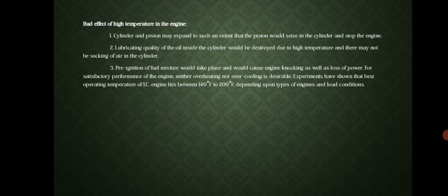Bad effects of high temperature in the cylinder. The cylinder and piston may expand to such an extent that the piston could seize in the cylinder and stop the engine. The lubricating quality of the oil inside the cylinder would be destroyed due to the high temperature, and there may not be proper sucking of air in the cylinder. Pre-ignition of the fuel mixture would take place and could cause engine knocking as well as loss of power.